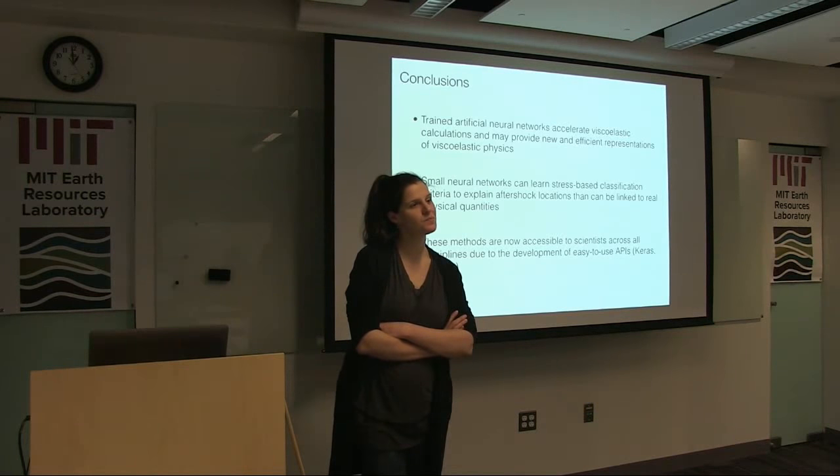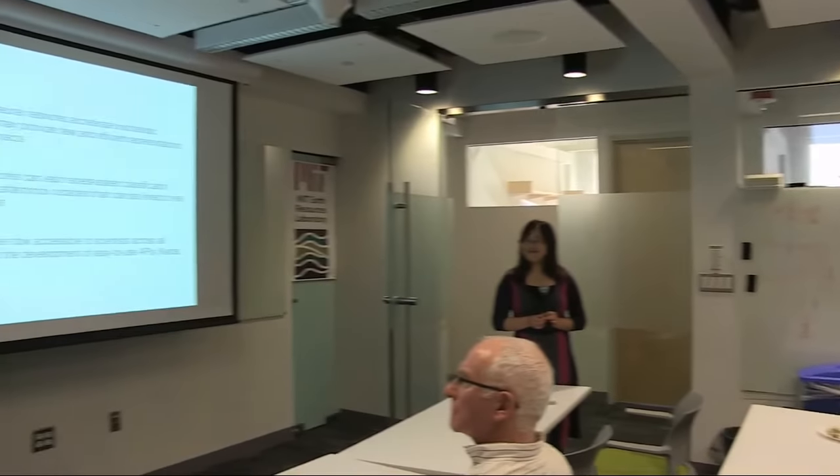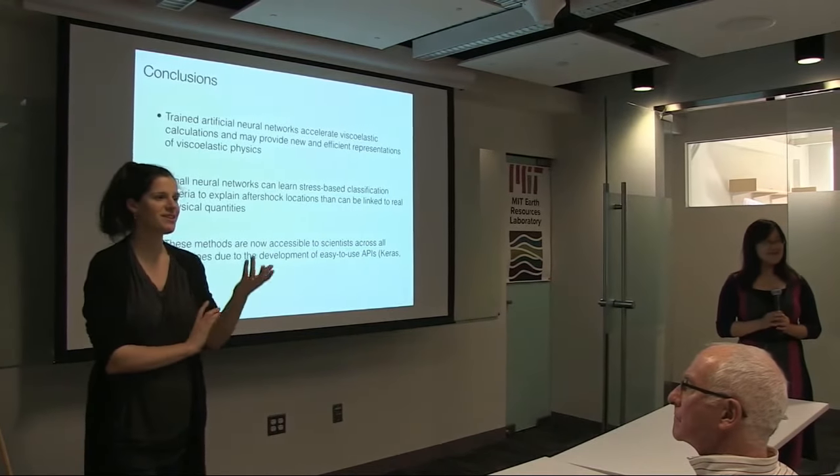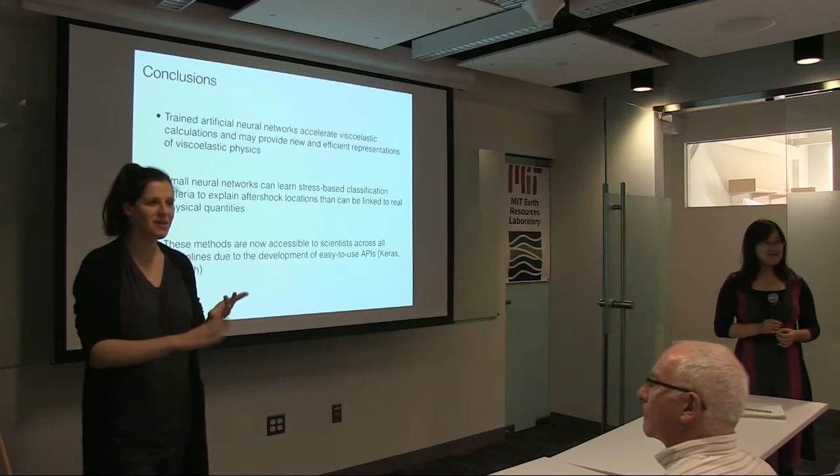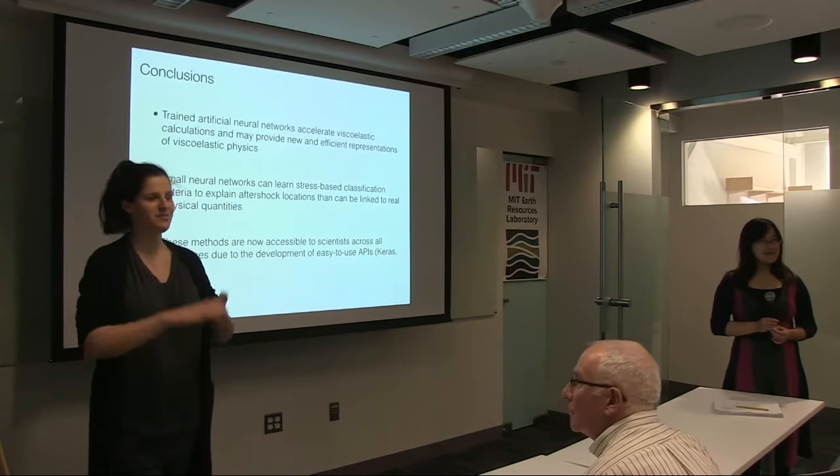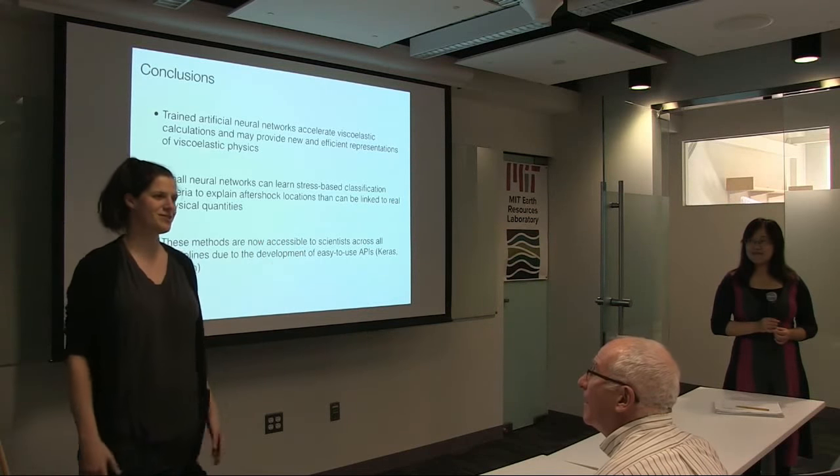For a large earthquake, either greater than 7 or a certain magnitude, they may have really large aftershocks. Those large aftershocks may act as a secondary main shock and trigger it. What I'm thinking about is the dynamic triggering system and also the nonlinear trigger between main shock and aftershock. Do you consider this a complexity? No, we don't. We focus totally on static elastic stress changes for now, to isolate this one part of the problem. But the cool thing about these approaches is that you could incorporate dynamic stress changes, poroelastic, viscoelastic, existing locations of geologic structures. You could incorporate all that kind of information.